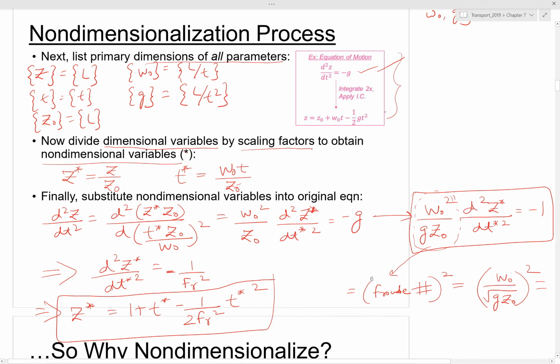What we have done is we have first non-dimensionalized the variables, the fundamental variables in this equation, Z and T, and then we cast this differential equation to tease out the Froude number and then express the equation in terms of a non-dimensional number, which is the Froude number, and then we solve it.